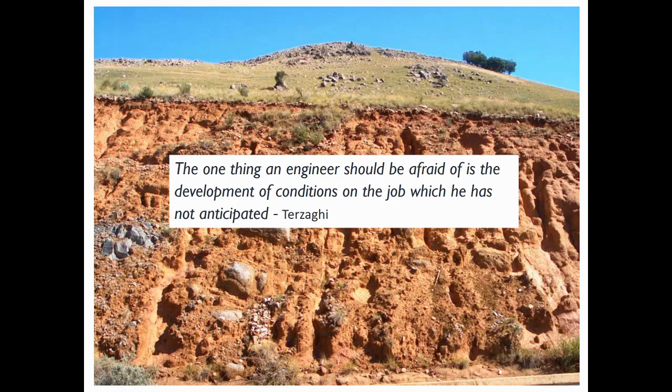Terzaghi, one of the very well-known soil scientists, said something that is very important. The one thing an engineer should be afraid of is the development of conditions on the job which he has not anticipated. In other words, if your soil or preliminary investigation on site was flawed, you didn't pick up the amount of clay or the abundance of rocks in the soil profile, or you think you're working on shallow bedrock.